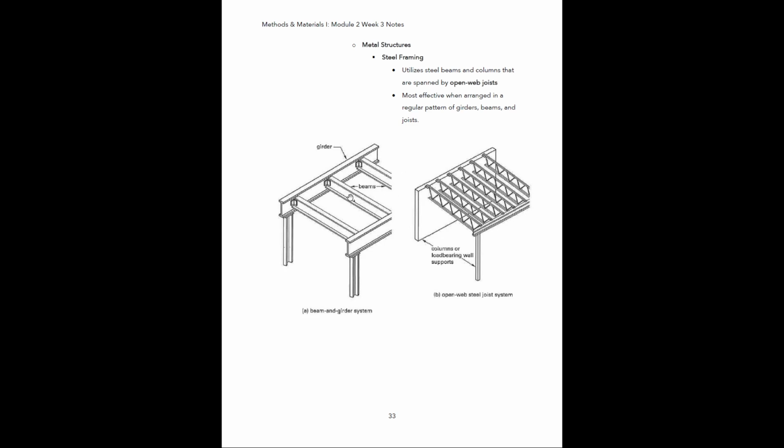There's going to be a standard spacing of all these, and then the girders are sitting on top of these steel columns. All of this is basically arranged in a grid, just like we talked about previously. These column lines will all be arranged by the engineer in a way that makes sense structurally. They can also be supported, so instead of just a column, you might also have a load-bearing wall. Here on the right, you can see we have a load-bearing wall.